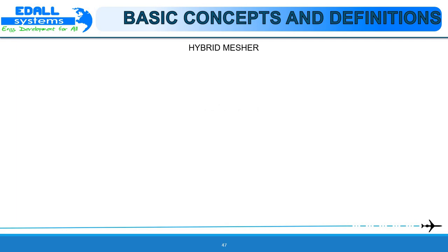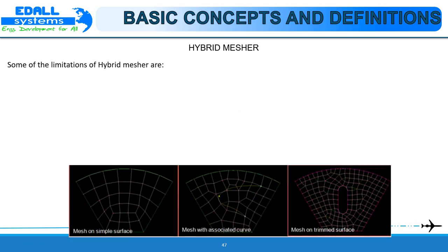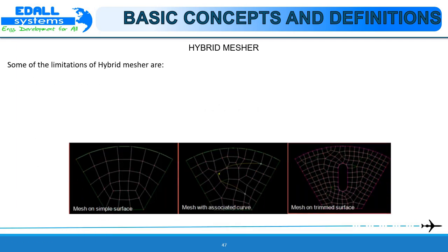Hybrid mesher. The hybrid mesher is a surface mesher that is used internally by TET meshers. It can be used for quad dominant mesh on any surface. The hybrid mesher recognizes mesh seeds and hard points, and its curvature check automatically refines mesh along highly curved edges. The mesh created by it is generally more regular or well ordered than paver, but not as regular as isomesh.